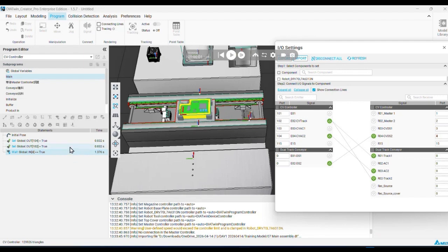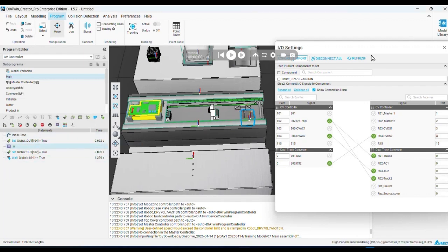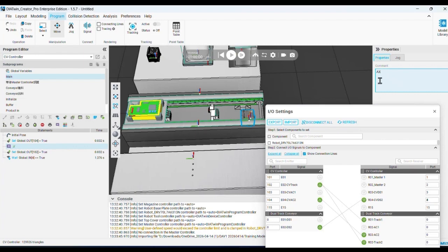So also, if we want to stop the conveyor, 104 means right here, right? Okay, AC air cylinder. If I need to control the air cylinder, we use 104. If we need to control the conveyor, we use 102. If we need to get the return signal from the sensor, we wait for port 4.